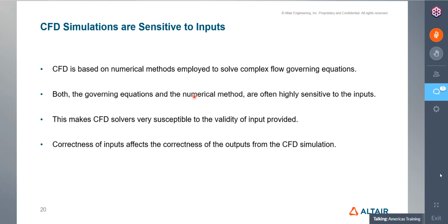Okay, so when we're talking about sensitivities, what I really want to discuss is what are some of the things that affect your answer? So that's kind of the short version of that. When you bring in a model, there's a lot of little things to consider that can have a big effect on your actual answer. So when we get any kind of CFD result, you've got to keep in mind that there's a lot of little things that will affect the actual solution. Things like your meshing, the actual physical models, and I'll go into what each one does.